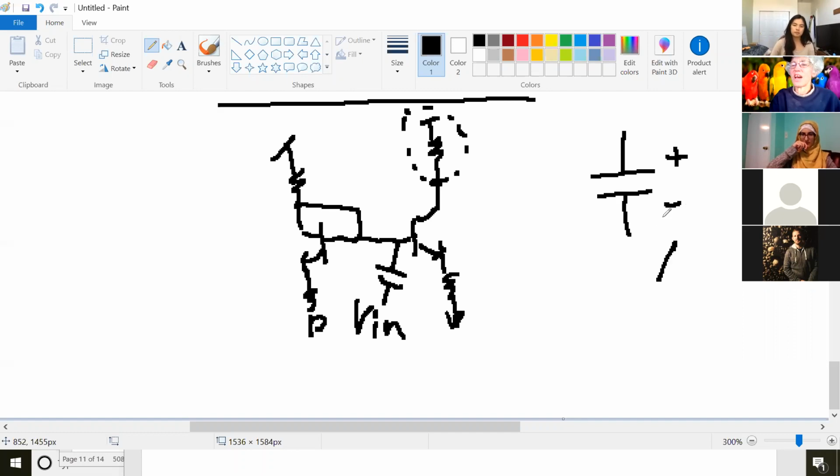So if this side moves fast, because the difference in the voltage between these two plates can't change instantaneously, this side has to move too. So this will only let the high frequency signals through. And what it'll do is whatever your original voltage on this node, it will just add the moving part of this signal through, not the DC part.